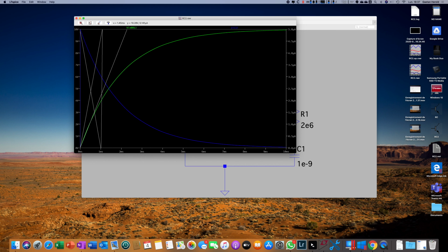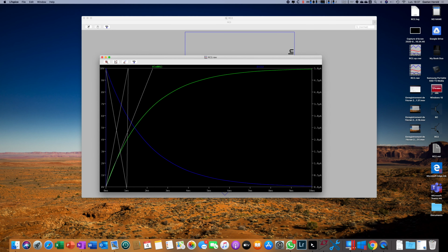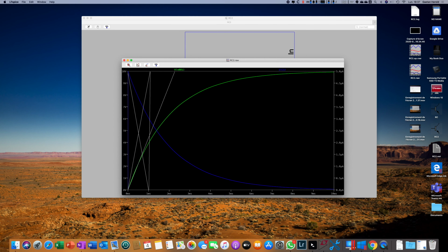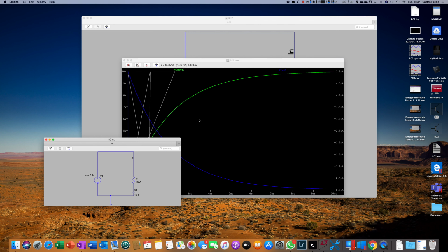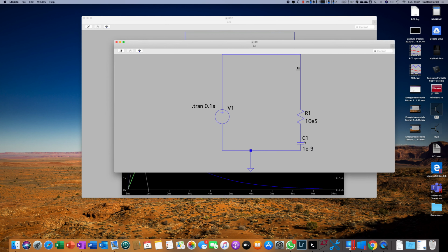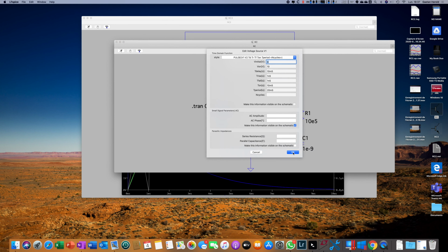Now, we are going to see another way of using these transient regimes, in really pulsating voltages. Here, I have prepared a small circuit for us. The difference is slight. It is here. We have the same initial value, the same on value. I simply create a periodic square signal. It's on for 10 milliseconds, it's off for another 10 milliseconds. So, T on equals 10 milliseconds and T period equals 20 milliseconds.